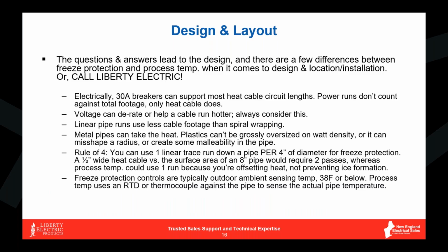Now, one thing that's important to note as well is when we're doing that design, if we went back to our chart from, say, 5 slides ago, and I'm using a 120 volt 5 watt a foot cable that I know maxes out at 275 feet on my circuit length, and let's say from where I'm bringing power inside the plant to where it's got to go in my process is, say, 75 feet. If I'm running just 10 gauge Romex to feed a J box near that pipe, that first 75 feet of pipe and wire does not count against your circuit length. So please understand that. That's a very important note.